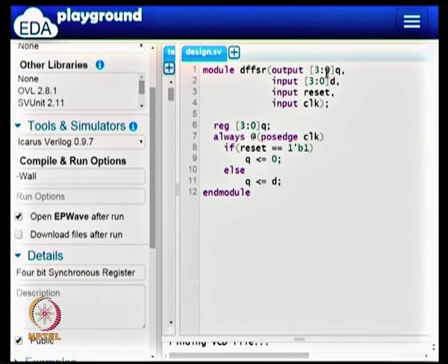So it is not correct to go back and ask, what is this software feature that I have? I have this software feature in C and C++, how do I do that in Verilog? That is the wrong way to approach hardware design. The way to look at it is, in hardware I want this, how do I model this in Verilog? So Verilog should not be thought about as a substitute for a sequential language like C or C++. Verilog is primarily for hardware modeling.